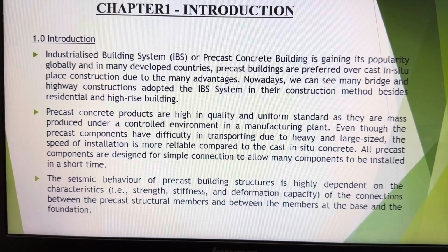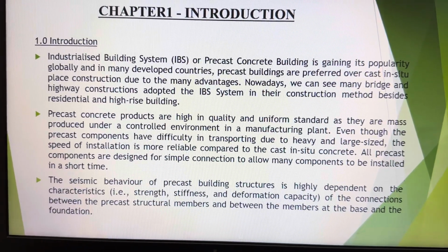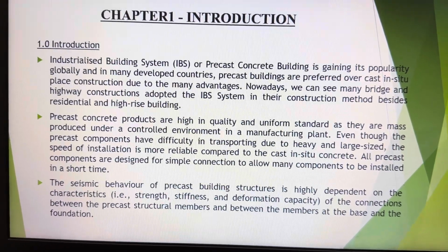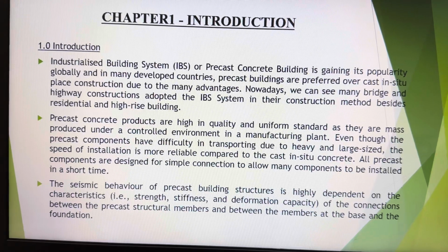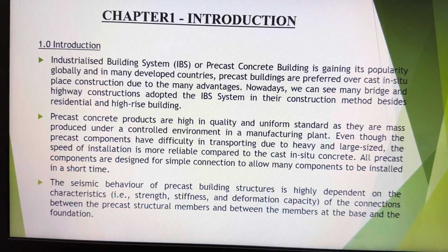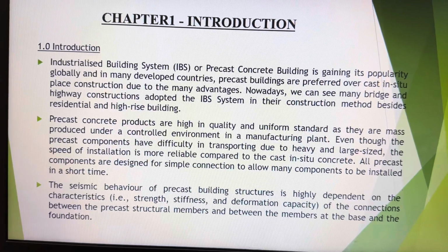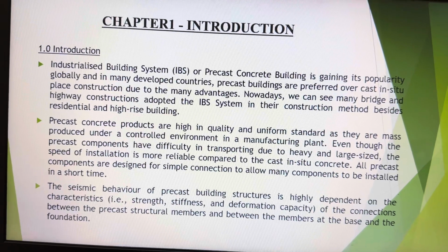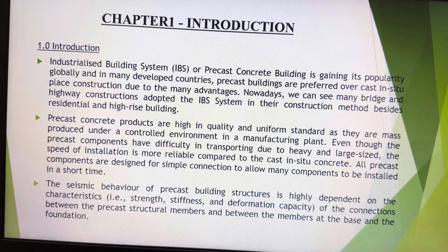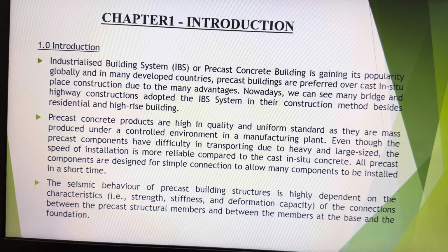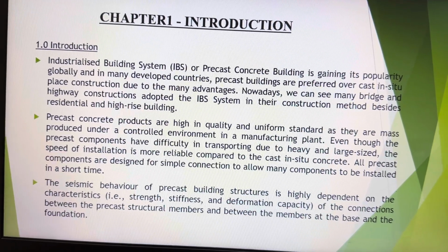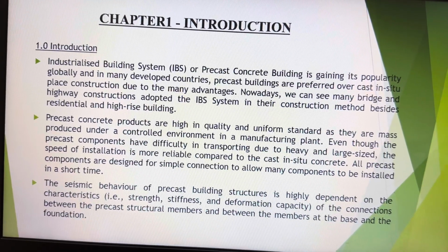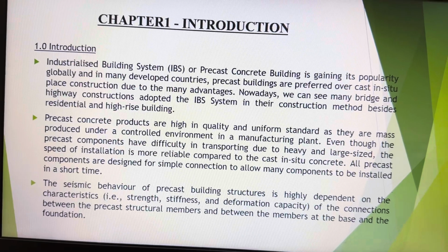in a manufacturing plant. Even though the precast components are difficult to transport due to heavy and large size, the speed of installation is more reliable compared to cast in situ concrete. All components are designed for simple connection to allow many components to be installed in a short time. The seismic behavior of precast building structure is highly dependent on the characteristics such as strength, stiffness, and deformation capacity of the connection between the precast structure members and between the members at the base and the foundation.